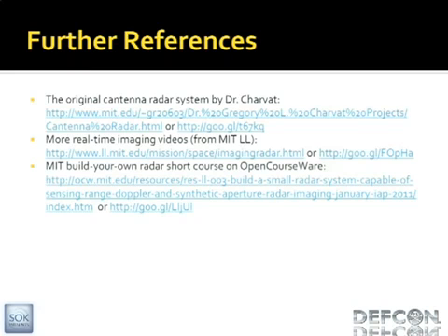The problem with this is you would have to band limit it some more. The way this works is it does actually extend past the Wi-Fi band a little bit. And that's why we only use it in kind of controlled environments. Basically, we don't want to step on anyone else's spectrum. So I wouldn't transmit a watt in that whole range. This is like 10 milliwatts. It's pretty low.